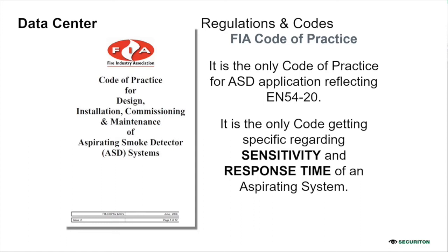They talk about sensitivity classes. These classes relate directly to the specifications in EN 54 Part 20. See, this relates to the whole aspiration system and not just the aspirating detector. So this kind of code talks about the complete system, not only the detector. These codes talk about Class A, which is very high sensitivity, required for the data center. Yes, the Class A application is used in data center installations.